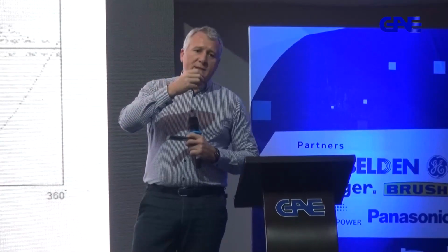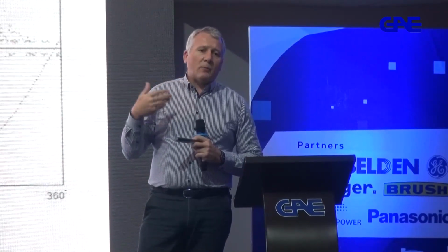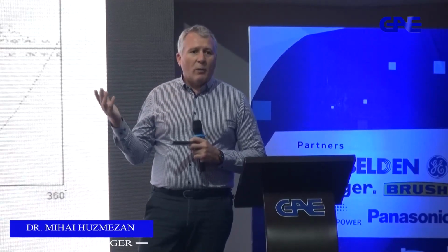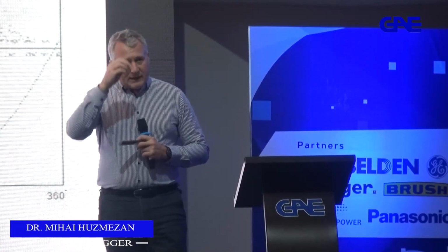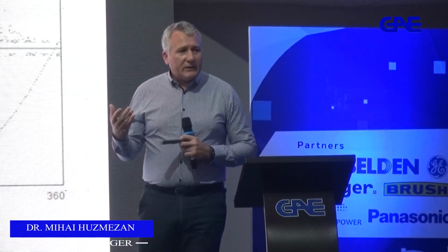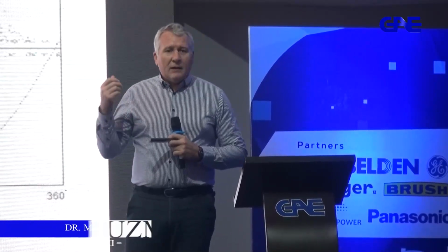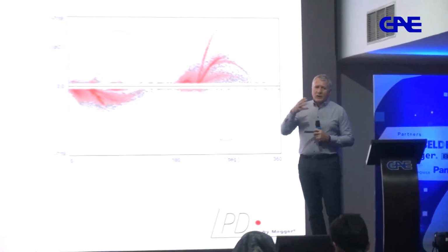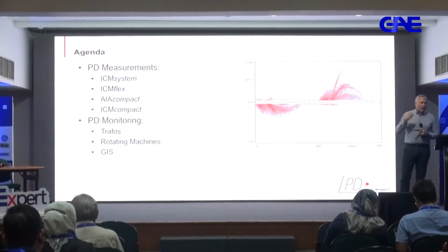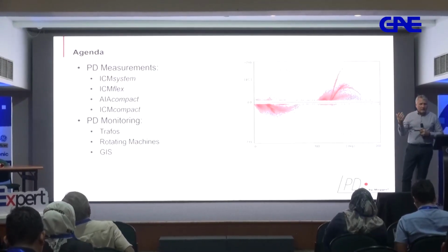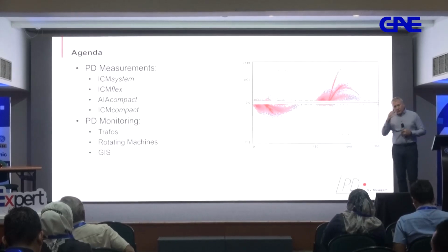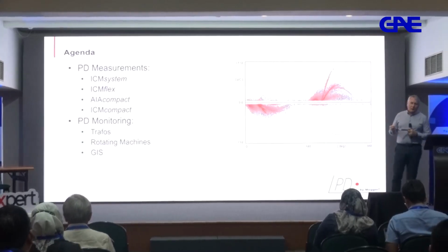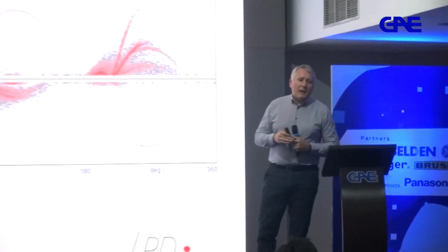So when you have an impulse like that, from an electromagnetic point of view, most likely you're going to create UHF radio waves. Equally, when you have an impulse like that, if it's very big, you may even hear it because there will be acoustic wave pressure that can be heard and measured. Sometimes such impulses and the movement of electrons will even be seen. So, for instance, you can look in a certain frequency spectrum and practically see discharges, and that's how that beautiful photography with those trees that you see is being made.